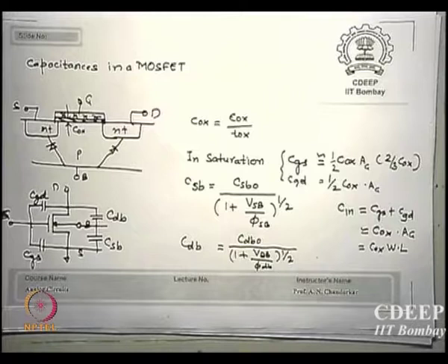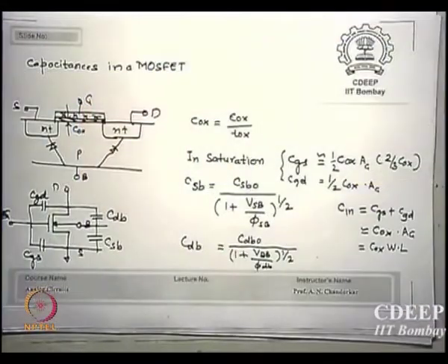So how can we do it? We are still working on less than a nanometer kind of oxide thicknesses. How do we do that? We are increasing epsilon proportionately so that T also can be increased, and capacitance is held. That is why it's called high K dielectrics. The new technologies use no silicon dioxide but dielectrics like hafnium oxide, hafnium oxynitrides, gallium oxide, lanthanum oxide, europium oxide.